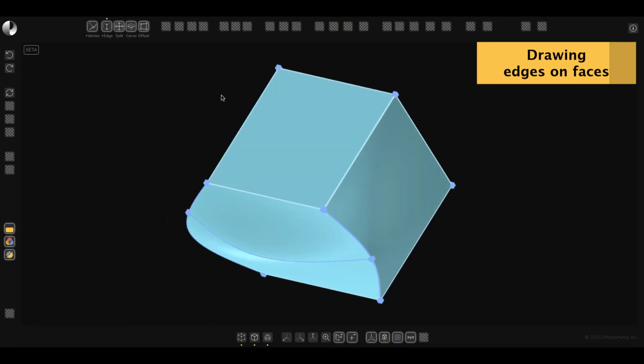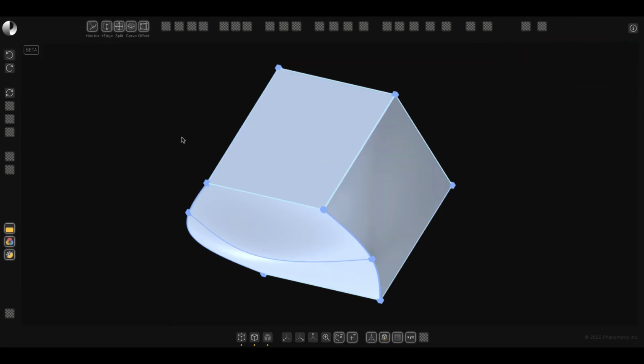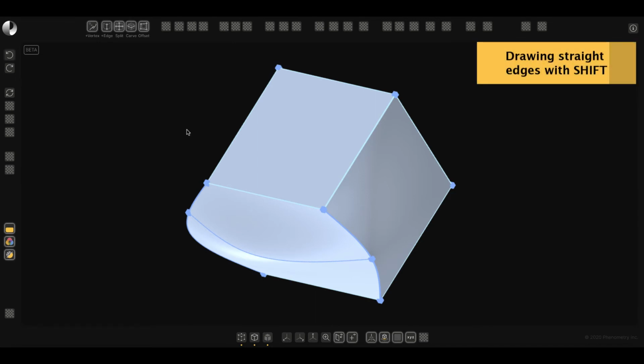As mentioned, you can do this also across more than one face, like I'm doing here, to draw 2 edges effectively on 2 faces. I will undo this. In addition, if while moving your mouse you have your Shift button pressed, after hitting E, the edge will be added linearly. So the movement will be linear, horizontally or vertically over your object. I will undo again.